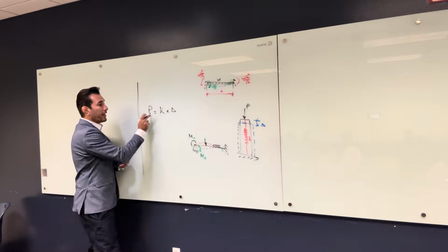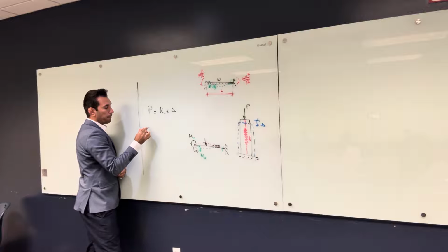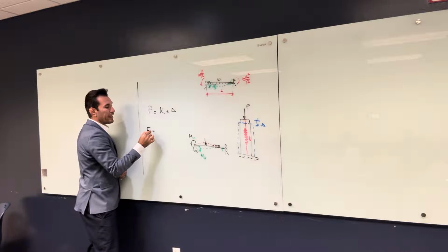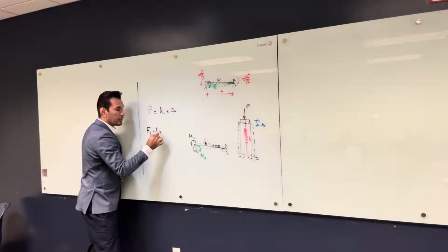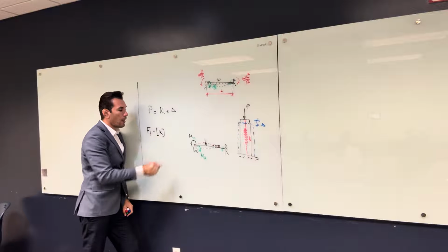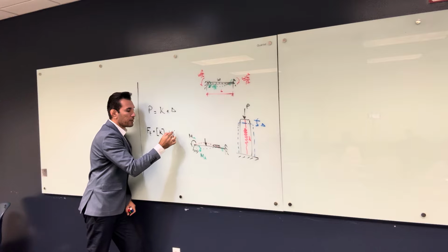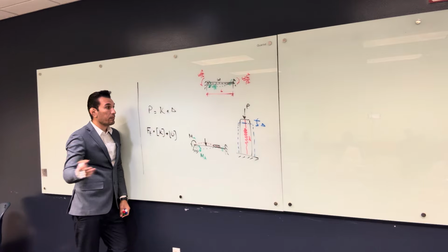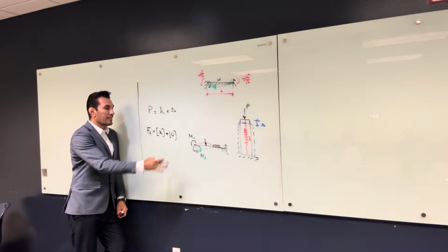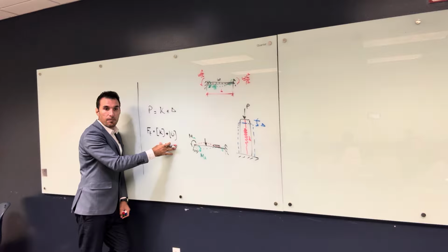So my load is gonna be equal to F total of both of them, is gonna be equal to a stiffness matrix K. We're gonna talk about this K, but it's the same thing like here, multiplied by delta. I'm gonna put it as D because this one is rotation. This D can be delta, can be theta. That is the governing rule of the stiffness method.